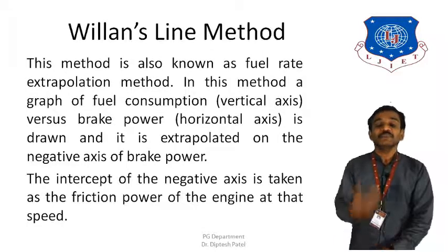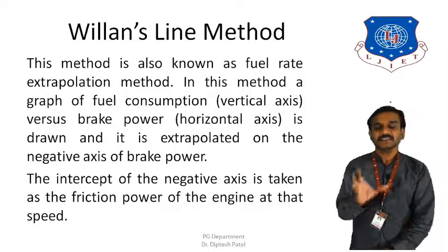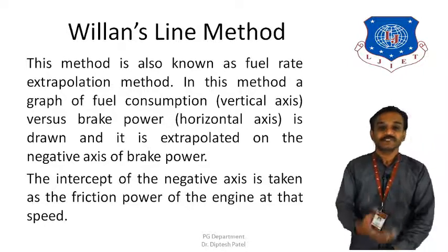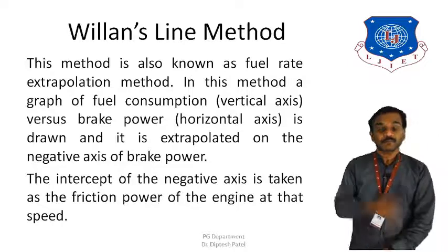Now how do you measure the friction power? There are various methods that can be used to measure the friction power, such as the Williams line method, the Morse test, or the simple motoring method.